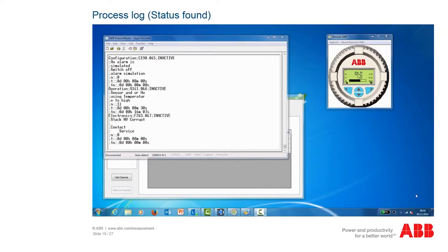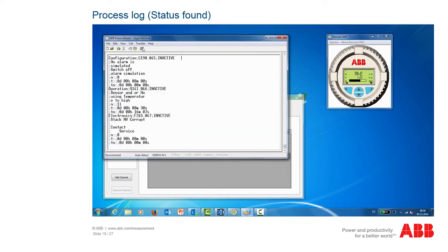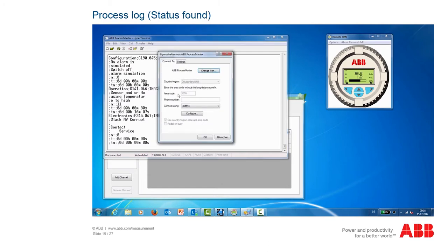In the process log, previously selected measured values from the transmitter are recorded in cycles and thus can be evaluated at a later point in time, e.g. with Microsoft Excel, and displayed graphically. This log and the measuring data recorded are particularly helpful for problems that occur occasionally.